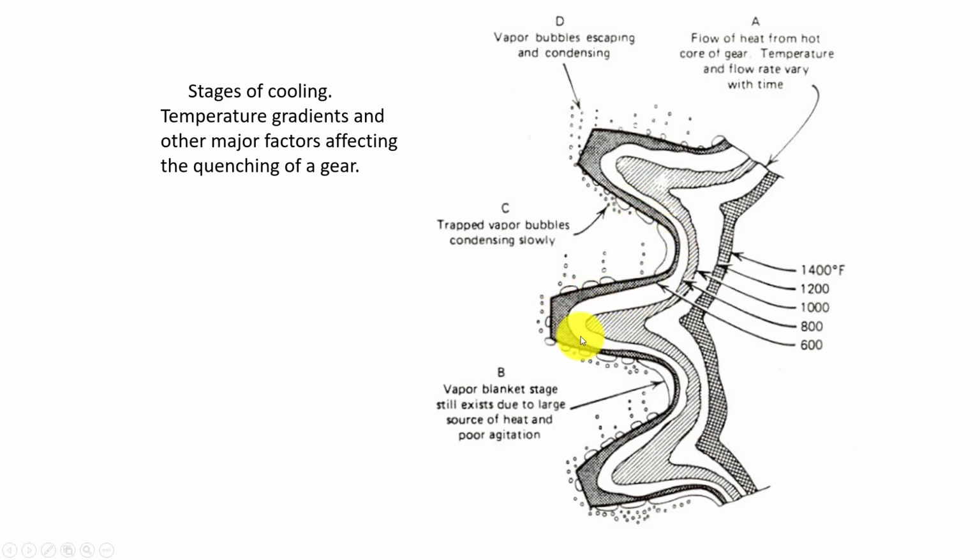This slide, I put this on here just because this is a gear profile, like a spur gear, and we would heat it up probably through an induction method, and then we would quench it, and you have a thinner mass here than this core, and what's going to happen is we're going to see the discharge, so we'd want a discharge vapor disruption happening, but the cooling rate is going to change, and we might see it being very hard due to the quenching rate on the outer surfaces here, and have a tougher core due to the heat rate not coming out as fast and pulling the heat out of the part, keeping this core of this tooth hard.